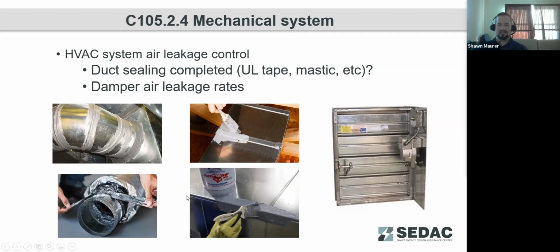But as soon as you get into a system with greater than 2 inches of pressure design, which is going to be most of your distribution ductwork, that ductwork does need to be sealed with mastics throughout. The only place where you're going to typically see the ductwork with less than an inch of water column design is going to be after VAV boxes in most situations.